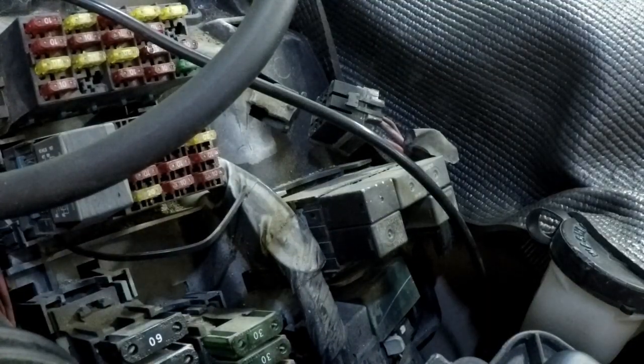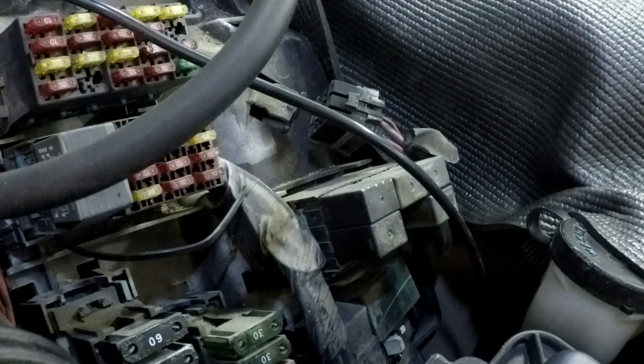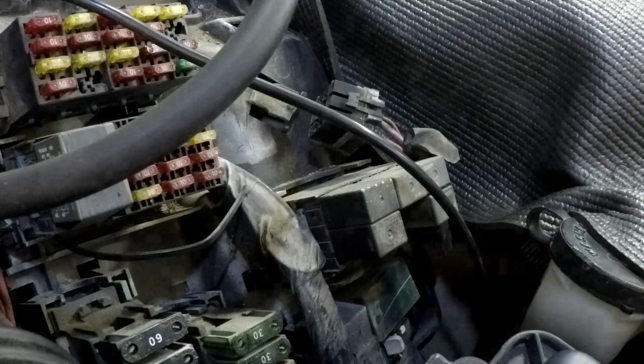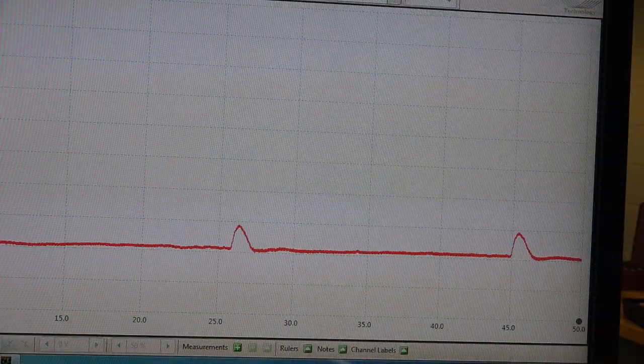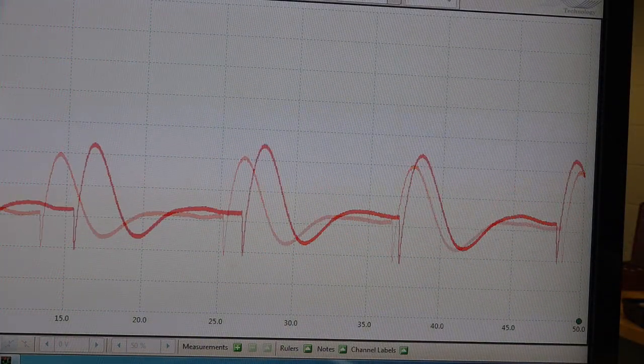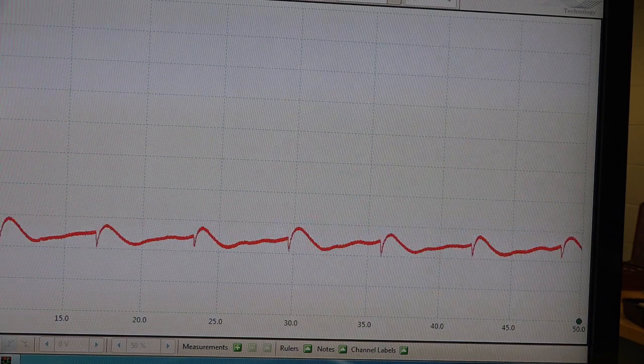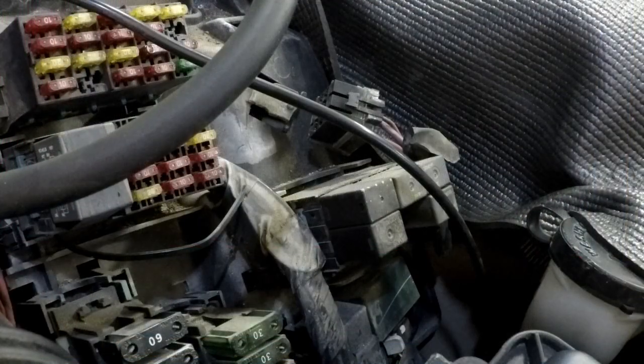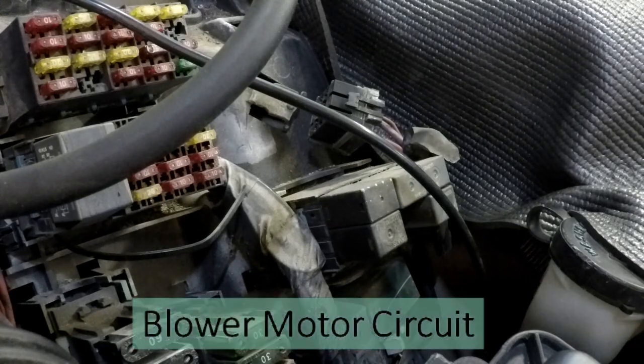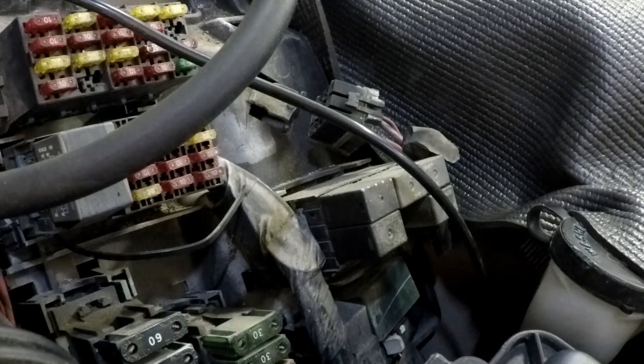So with the inadvertent relay removed, that should have taken out a whole bunch of lighting, things like that would be on. And it appears that I still have the drain. Watch it. Yep, there it goes. So that's telling me that it does happen to be that blower motor. So we need to take a look at the schematic and see whether the blower motor itself is doing it or whether something else is commanding it up or down.